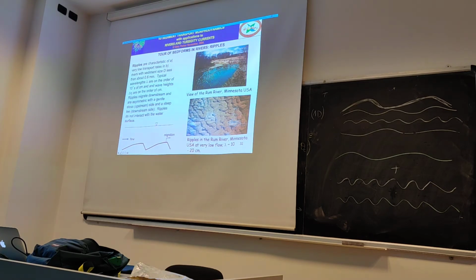You are already familiar with sediment transport, at least in a different way. So you know that you need to apply a finite stress to the bed for the sediment to move. Okay, so if the stress is too low, the sediment will stay still. If you exceed some threshold in the shear stress, or some non-dimensional form of the shear stress, it will start to move.